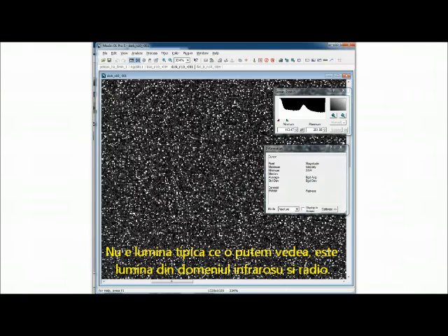Now, it's typically not light that you see. It's usually in the infrared and radio. But that infrared light that your CCD chip itself is giving off is actually something the CCD chip is sensitive to and will record as a thermal signal. In other words, the chip is imaging itself. It seems kind of ironic, really, but it's the truth. We have to deal with that.